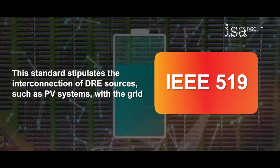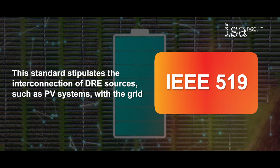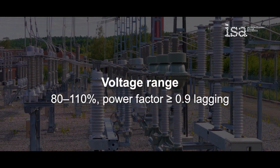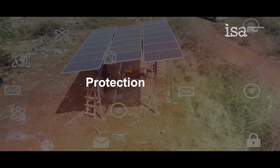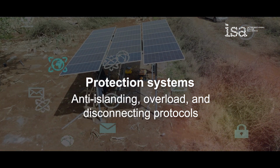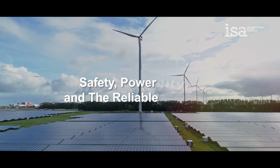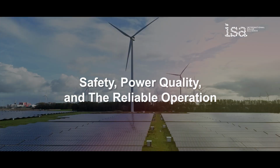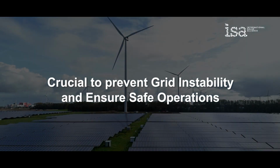This standard stipulates the interconnection of DRE sources, such as PV systems, with the grid. Voltage range: 80 to 110%. Power factor greater than or equal to 0.9 lagging. Protection systems: anti-islanding, overload, and disconnecting protocols. These standards ensure safety, power quality, and the reliable operation of the grid. Strict adherence to these specifications is crucial to prevent grid instability and ensure safe operations.